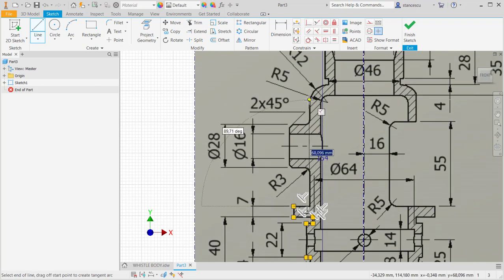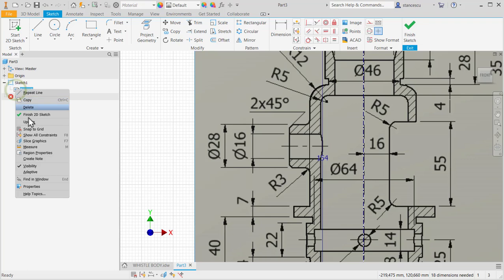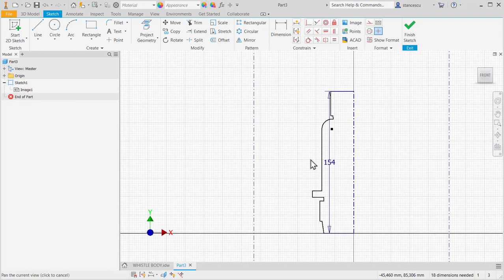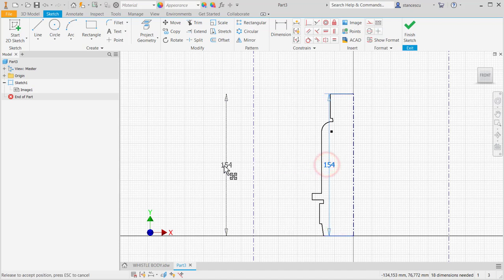I draw only the external revolution contour. Now I keep pressed the left button of the mouse and I go to the end of the previous contour. Now I make this image not visible, you see here, visibility, and I have my drawing. Very useful.